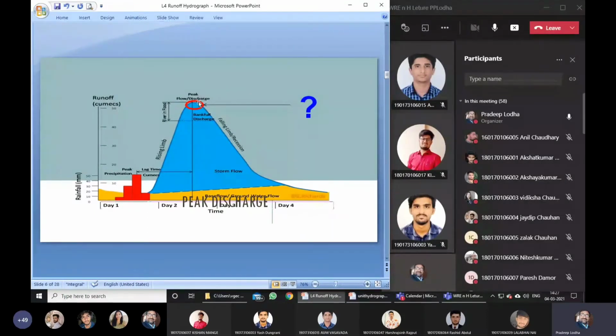Now this peak is here, which I already explained to you. This is the falling limb or recession limb. This is storm flow, and this is base flow, groundwater flow, or normal flow, you could say. This is lag time, which I have already explained. This is peak precipitation here, and this is runoff Qmax, etc. This is a different storm on day 1, day 2, day 3, day 4. So the hydrograph lasted for 4 days, not the rainfall event. The rainfall event lasted only a few hours, 6, 7, 8 hours.